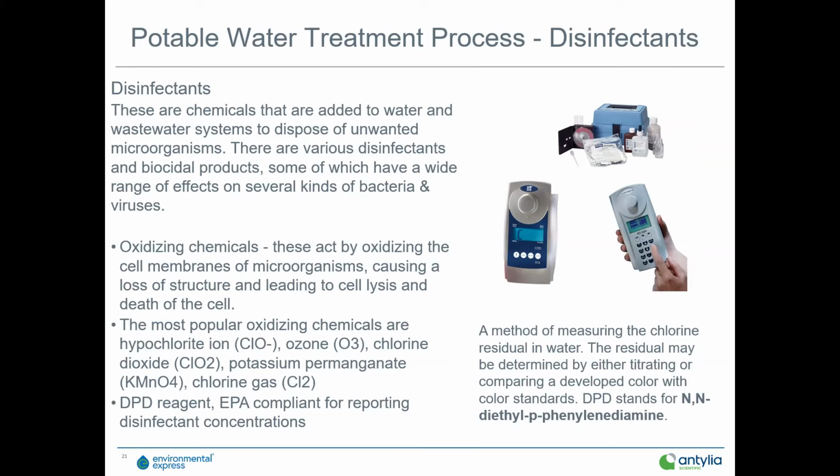One good breath of chlorine gas and you're in trouble. 2 breaths and you're really in trouble. But most plants now have been converting to the much safer hypochlorite ion, whether it's sodium or calcium. It's easier to handle, it's easier to store. There just isn't the liability issues when compared to chlorine gas.